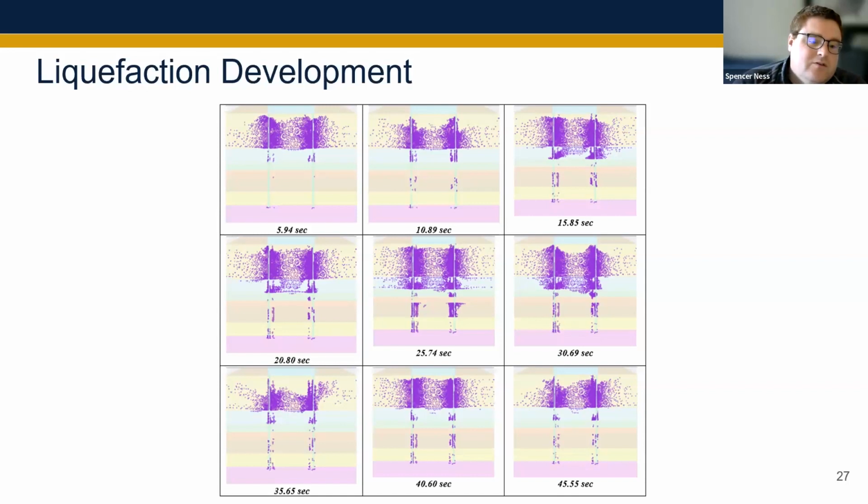But importantly, with this foundation, the way it's designed with these tie-down points, we are seeing some densification of this upper layer, which is why we believe we're not getting as many liquefaction points directly below the cap. The increase of effective stress from those tie downs pulling down on the upper foundation is impacting the effective stress development. And that's an important part of how this particular foundation works. And it's also great to see that the constitutive model is capturing that as well.